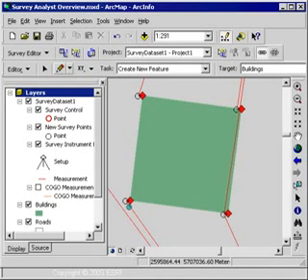In other words, I can link from the building corner to the survey point or from the survey point to the building corner. This link information, when I save this session, would be stored with the building corners, or the GIS feature. So now that I have the links established for that building, I want to update the geometry. I want to move it in coordinate space.